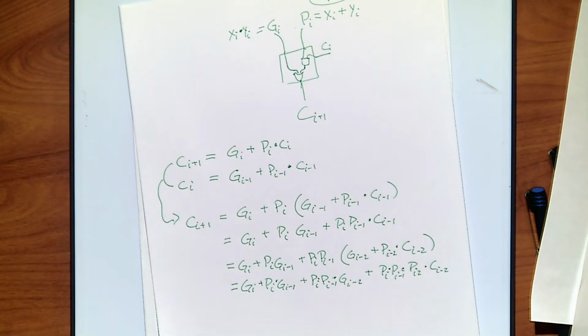This is a two-input gate, a three-input gate, a four-input gate. So the AND gate is bringing four inputs to the AND gate, four inputs to the OR gate. Add another level, you have one more. So you get five. It grows linearly with the input data. It's growing in space.